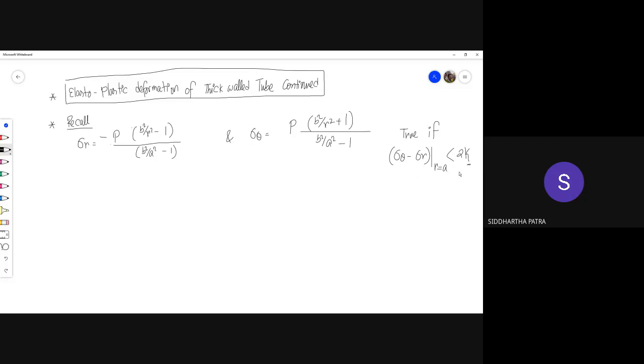So it's not as if, if the inner radius starts yielding, or let's say plastic deformation has reached a certain radius of C, for the rest of the geometry we could write this expression. No, this expression can only be written when the entire geometry is elastic.